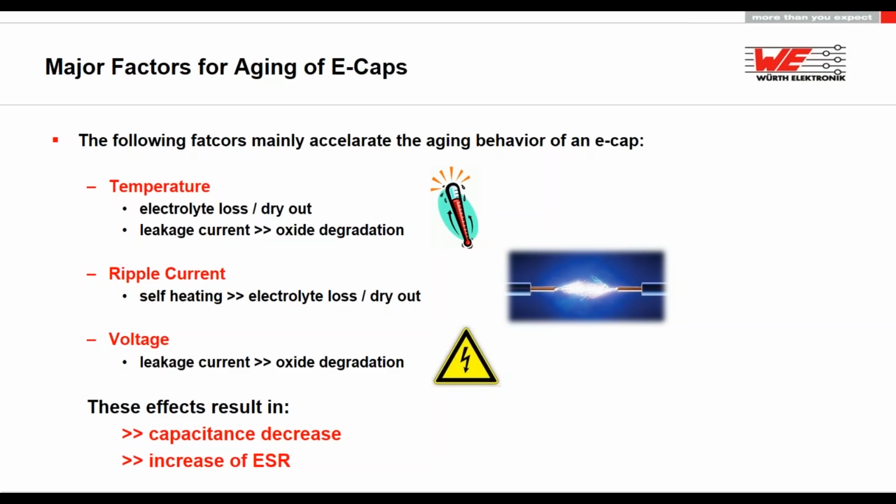And if it comes to voltage, if you get on a higher level as stated in the data sheet, for example, you have a 400 volt type, if you would apply 450 volt, you can damage the ECAP. You have a certain surge range, which would be 10%. So normally by the JIS standards, by Japanese industry standards, 10% is something you can run as surge.